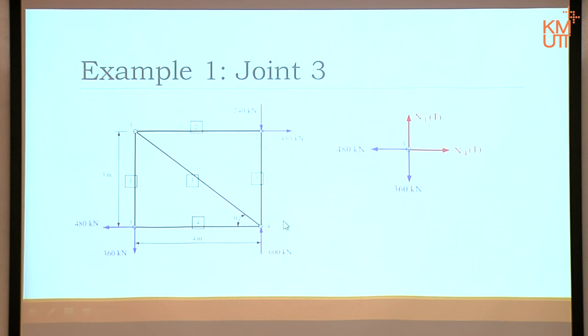Then you see the picture, you can guess what happens next, sigma Fx, sigma Fy. Then you get the 2 internal forces. Okay? Now because we're going to keep using that picture, now that we have analyzed that, I must go and mark it there. Right? So it means that now my joint 4 doesn't have 3 unknowns anymore, right? Because I know N4 already. So at this point in time, my joint 4 has just 2 unknowns, right? My joint 1 also has 2 unknowns, my joint 2 also has 2 unknowns.